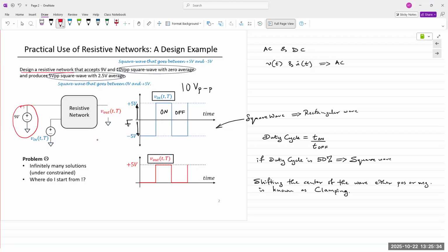And that's easily done. We use a voltage divider network, use multiple resistors in series, and we can obtain any value we want. If we have 9 resistors, each with equal value, 100 ohms or 1 kilo ohm or 10 kilo ohms, and you connect them all in series, you can have 1, 2, 3, 4, 5, 6, 7, 8, 9 volts, 9 levels of voltage all coming out. Okay, so voltage division is an easy and quick way to implement that kind of voltage transfer.